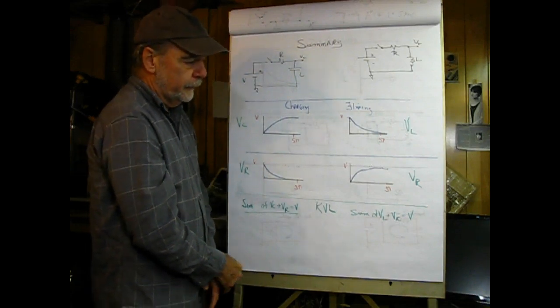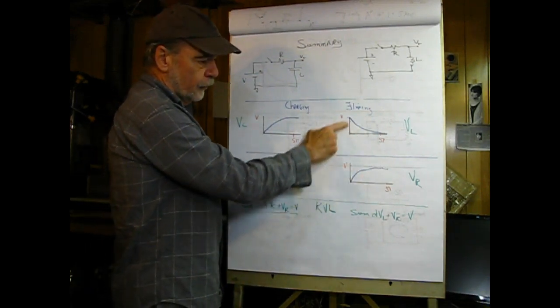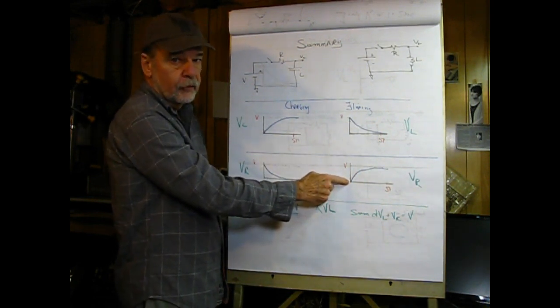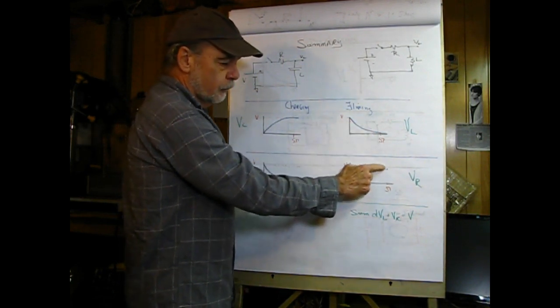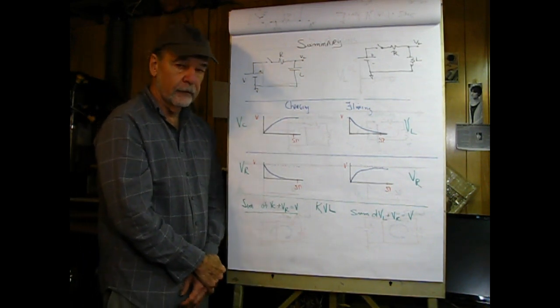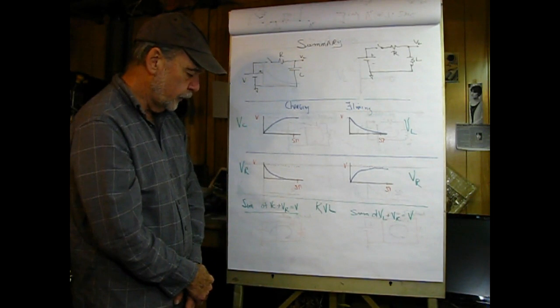In an inductor, again, the sum of these two has to be equal to V, since all the voltage is across the inductor and zero across the resistor. So as time passes, the voltage across the inductor drops, the voltage across the resistor rises, and at 5 tau is considered to be equal to V. That would be the voltage across the resistance is equal to V.